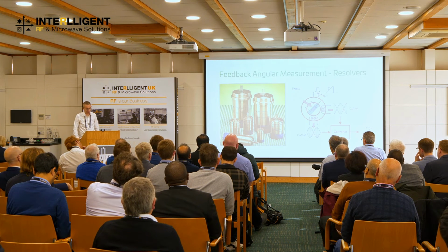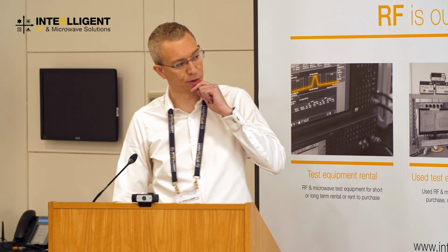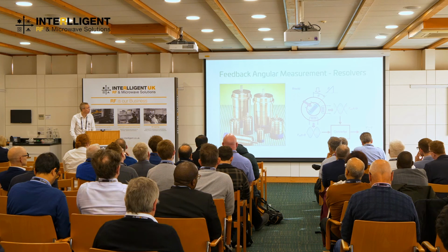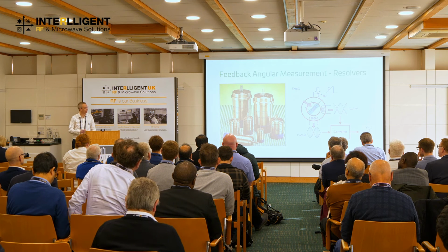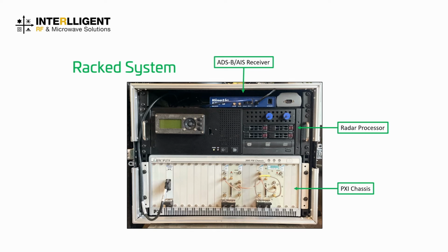Now, the scanner that came off this helicopter used these Muirhead resolvers to provide continuous measurement of angle. They deliver accuracy in the orders of sort of hundredths of a degree of resolution, and they are fabulously expensive. The resolvers are excited with a simple sinusoid, and what they deliver are two sinusoids that, when processed, give you a continuous angle measurement. Fortunately, nowadays, there are digital chips that will take those two components and give you a digital readout of angle.